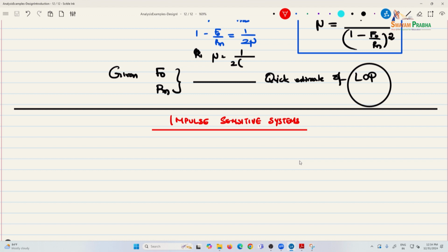Keep in mind, we talk about a response modification factor. Be careful when you talk to people in a seismic design world or you are working there. It also represents ductility, but there it represents the ductility you are designing it for. There it is only one thing, you have a capacity, elastic capacity. Elastic capacity is whatever you are designing, and then you apply, higher the mu, higher the ductility. It can go from 1 through 8. Costs vary for different systems, and so there it is used more from what I have shown out here. The mu is equal to 1 minus F naught by Rn, but just keep that in mind.